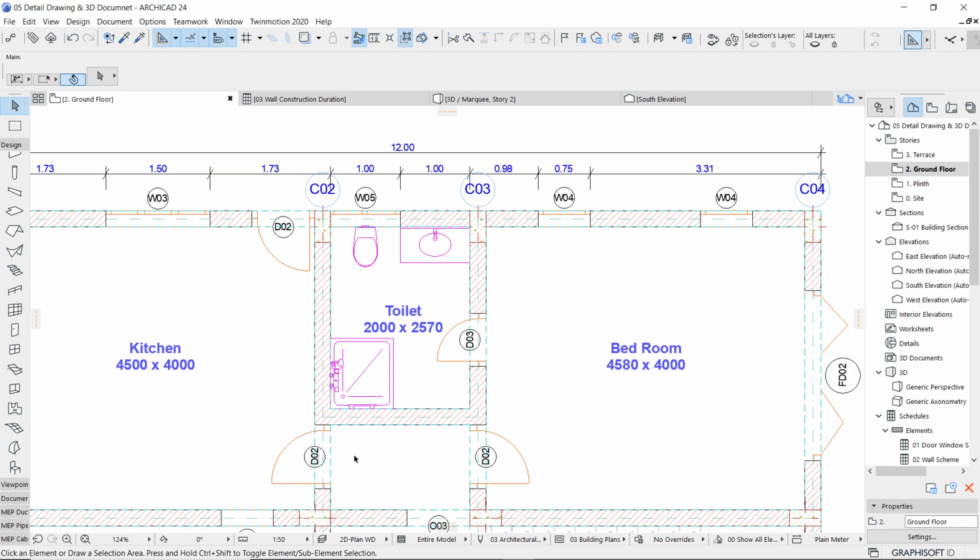What I'm supposed to do now is, on a single sheet itself, print my entire floor plan as a key plan, and the toilet area, that much of area I'll enlarge and print at a suitable